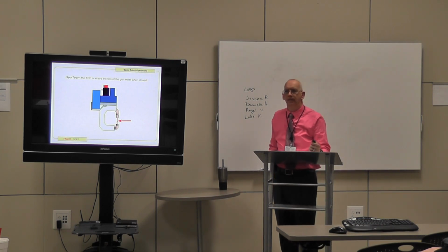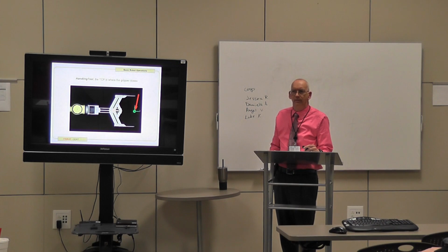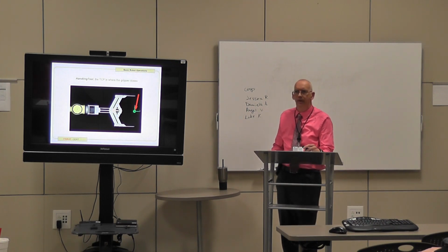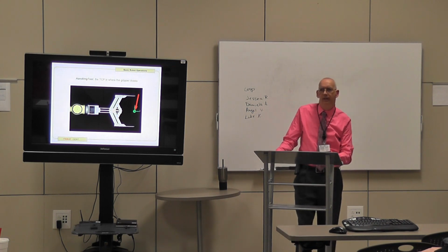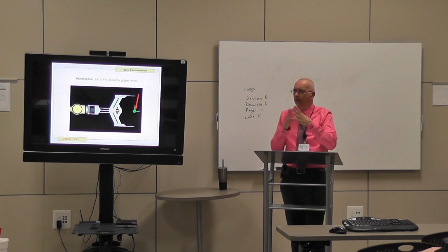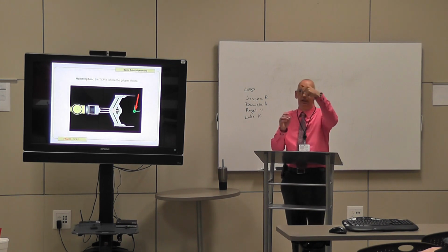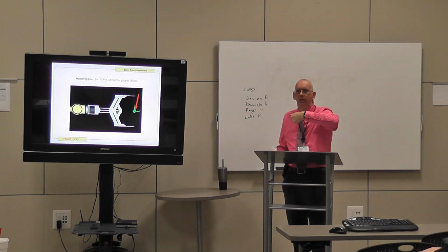Is that the same thing with the gripper that we have on the robots now? Yep, that's going to be the same thing. I'm getting to that. Look at that, hammering tool. Same thing. It's when you close that gripper that you find your TCP, because that gripper could change depending on the size. Our gripper is very small, but the thing about it is, it comes straight through.